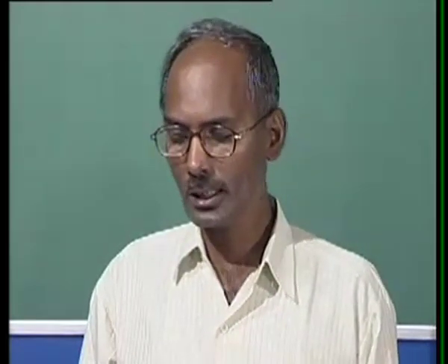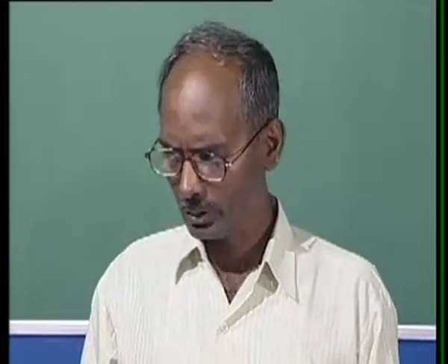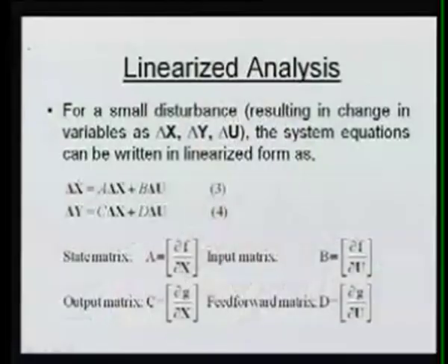So this x0 is the minimum information. For example, if you remember in the load flow, normally we take voltage and angle as the state variables because these are the only two minimum pieces of information from which we can calculate the rest of the system parameters, or you can say performance.